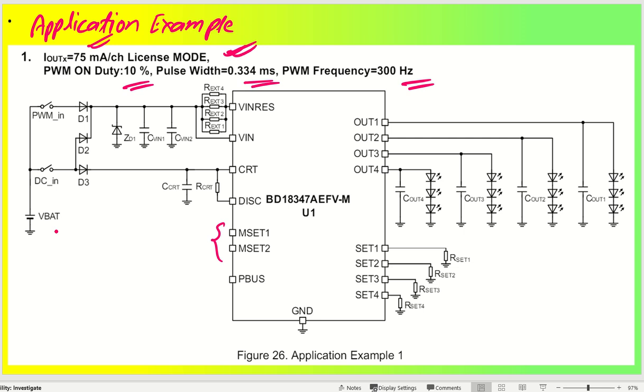Here one MOSFET will be used to do that job. Here also one MOSFET will be used to switch on or switch off the input voltage using the VBAT. VBAT is nothing but the supply voltage that is coming from either a battery, or it can come from some regulated power supply output. And these are the diodes that give you input protection, and this is the ESD protection, which is going to be MOVs.